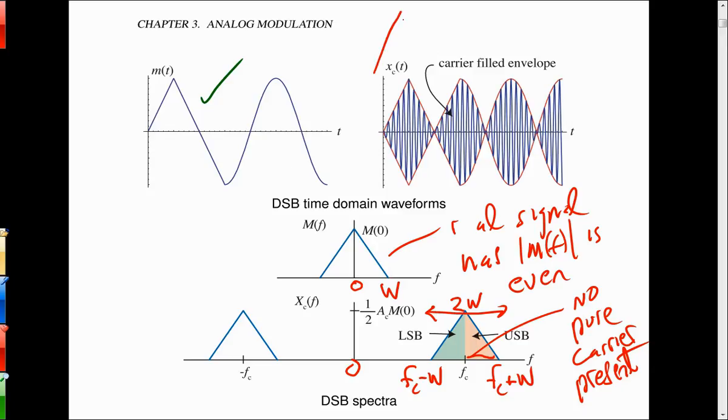If I add in the pure carrier, this thing comes down, and I'll just draw it more as a sine wave, so you can think of that as pulling up, and this is pulling down. I didn't draw it symmetrically, but now it's like the teeth of a comb, or like my fingers were together with the two waveform envelopes overlapping, and now I pull them apart. So now they're not touching anymore. Because of that bias added in there, of pure carrier, that allows it to separate like that.